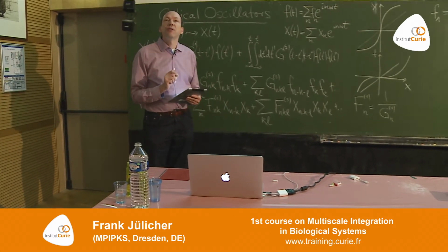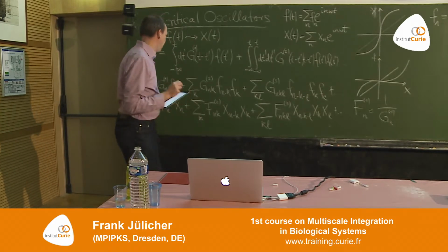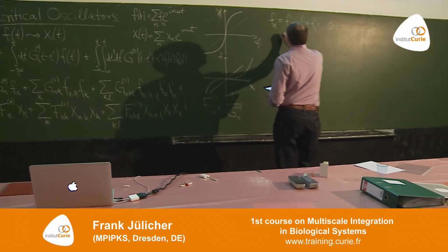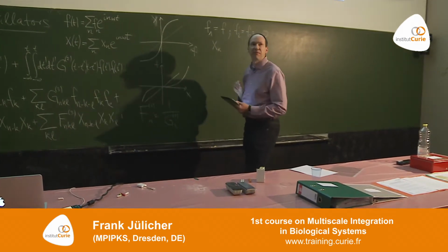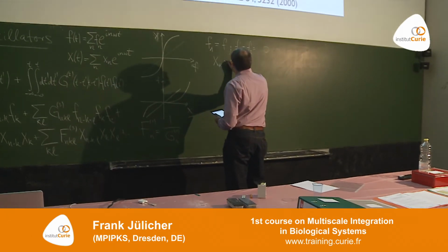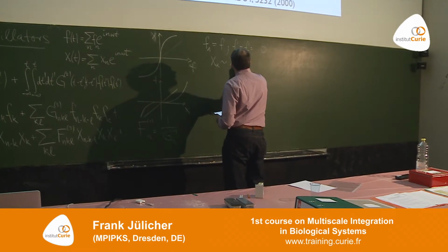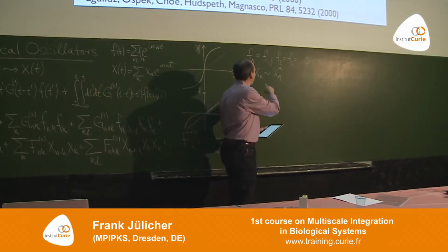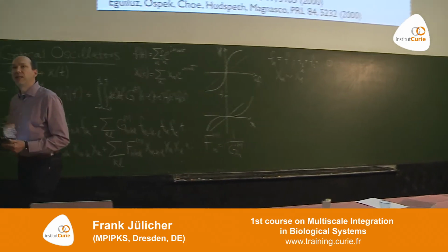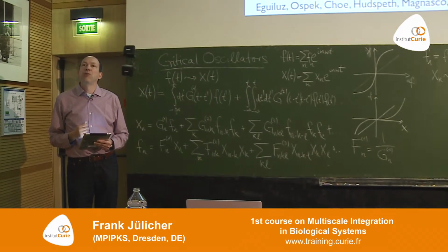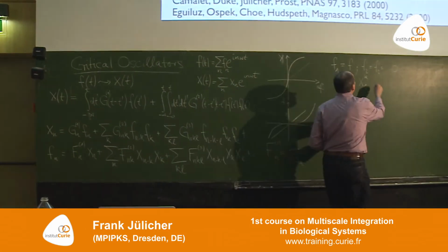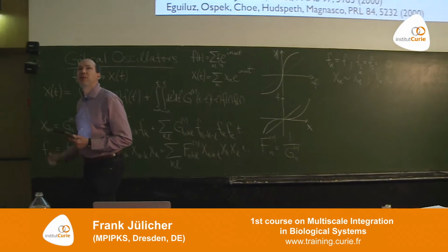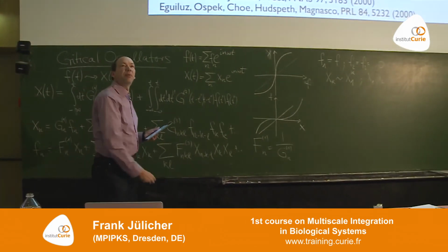Now, if we go to very weak forces, the responses will also be small, because as x goes to 0, f goes to 0. And one can show, by studying this equation a bit, that if I look at some kth higher harmonic of the response, xk, it scales as the fundamental mode x1 to the power k. So if we have weak responses, higher harmonics are even smaller. If x1 is a small number, xk is much smaller. Because of that, we can make a limited expansion and just focus on the lowest modes. So I will only consider the response of x1 and of x2, the second harmonic, which, as you'll see, is generated by quadratic terms. But the same argument can be continued to higher modes.